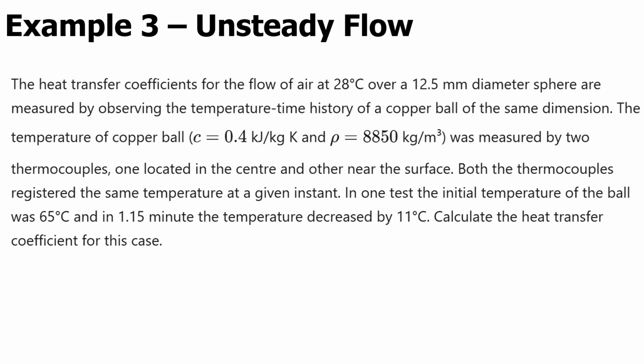Here's the problem. We are measuring the heat transfer coefficient for air flowing at 28 degrees Celsius over a 12.5 millimeter diameter copper sphere. The copper ball has a specific heat capacity of 0.4 kilojoules per kilogram Kelvin and a density rho of 8850 kilograms per meter cubed.